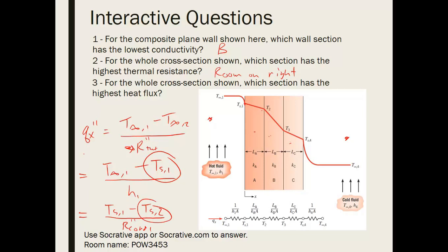This is a fact that could come in handy when you're doing heat transfer analysis for a plane wall at steady state. Use this thermal resistance method to get flux for the overall system, but because the flux going through is equal and independent of x, you can create these extra relationships and solve for intermediate surface temperatures.